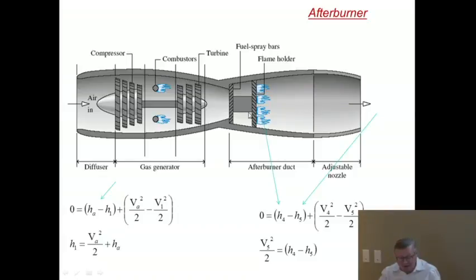That is simply going to be a second addition of heat, followed then by a nozzle, which transforms this additional enthalpy to kinetic energy. So that is what the afterburner does. You take this enthalpy here, you add enthalpy H5 to it, and then you transform the whole thing into kinetic energy, which is of course higher because you have transformed the heat into kinetic energy and therefore propulsion.